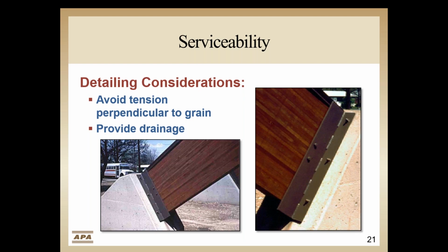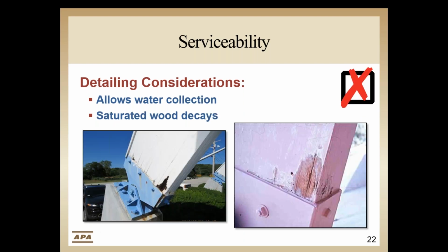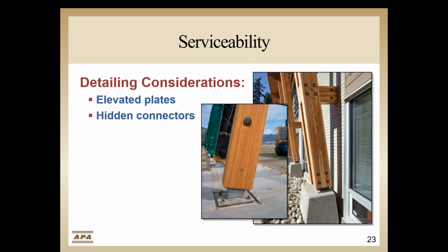It is best to use connecting hardware that breathes and drains. Notice the cap flashing on the beam's top edge to discourage rainwater from being absorbed into the top of the wood section and direct water away from the wood. If water does get in, you need to design connections that let it out and let the end section breathe. Trapped moisture quickly leads to fungal growth and decay under the right conditions. Details often include weeps and vents in shoe-type connection hardware to facilitate venting, which can be fine. But be careful, sometimes weep holes clog. Make sure the connection allows the water to drain.